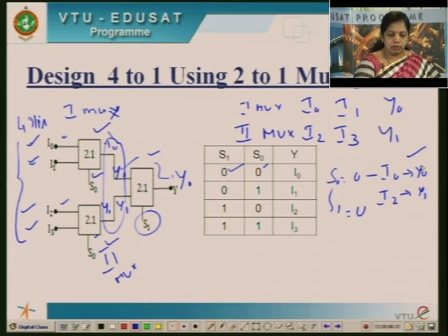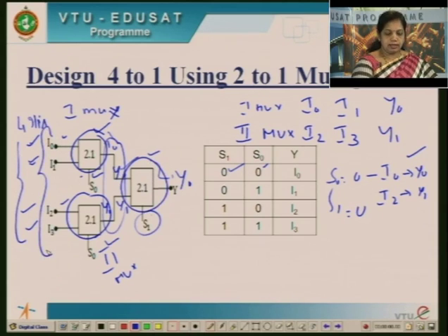So even though we are using 2:1 mux, 3 2:1 mux together are acting as 4:1 mux. S0 and S1 act simultaneously and you will get output at the final multiplexer, that is the third 2:1 mux.